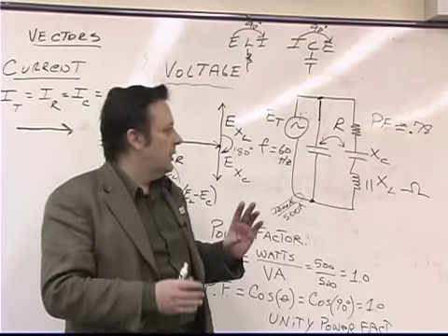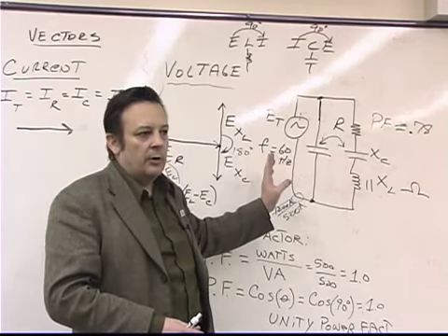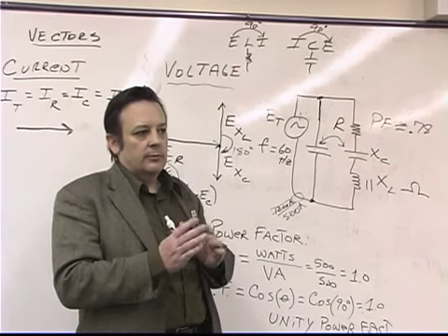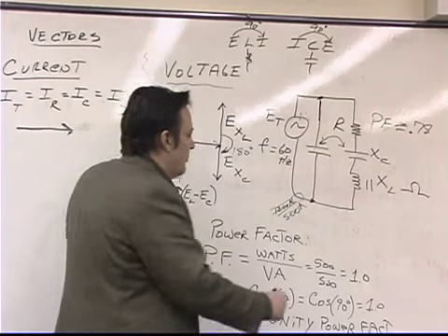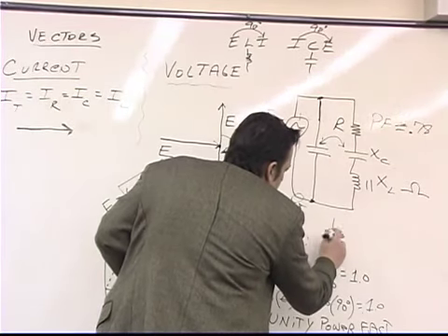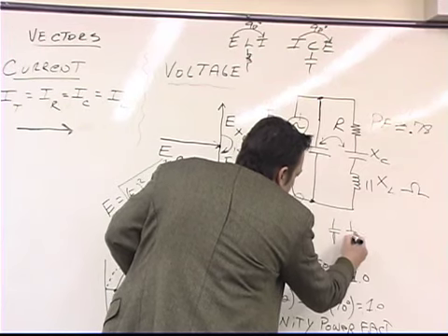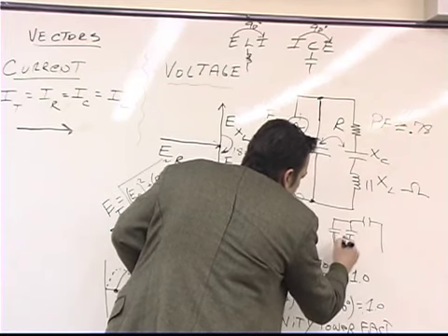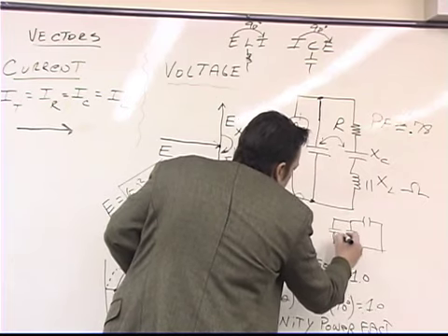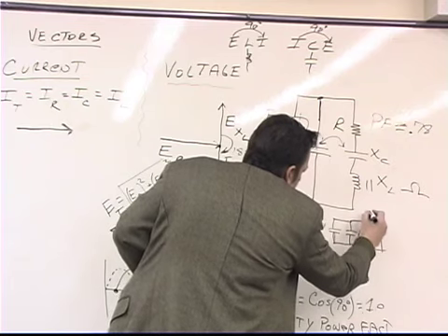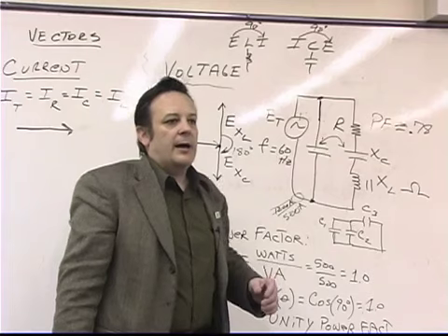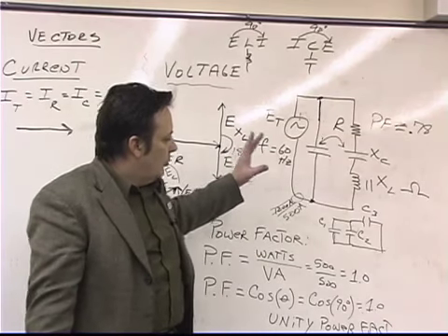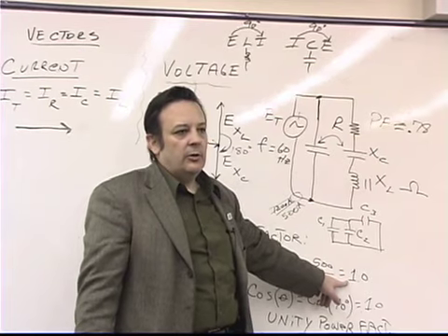So you have to have circuitry that's sensing what the power factor is in real time, and then it's switching in whatever capacitance is necessary to offset that power factor. And so in reality, what we end up with is a rack of capacitors that are in series and parallel configurations with each other. And so we end up with, you know, like a C1, a C2, a C3, and then in between all of those capacitors, we have relays. And we're able to switch those capacitors on and off so that we don't exceed a unity power factor.